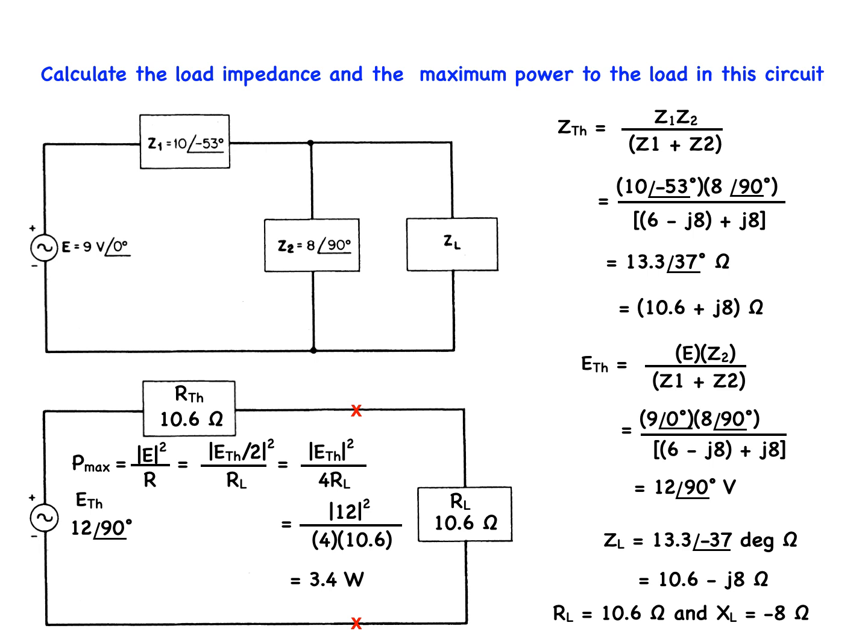It's interesting to note here that the maximum power that can be delivered from a circuit happens when the load resistance is equal to the internal resistance of the supply, or when dealing with impedances values, the maximum draw from the source is given by the load, which is the conjugate of the internal impedance. In this case, the internal impedance of the source is the Thevenin impedance.